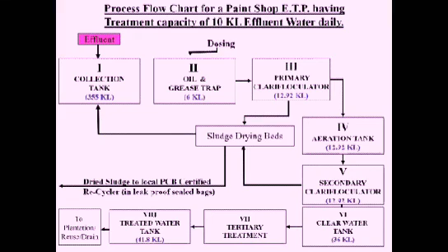This, in this case, is having 36 kL capacity. From here, if we are not attempting to make this water potable, we can directly use it for plantation or reuse it in any of the utilities in our factory organization, or we can put it in the stormwater drain also, in case, of course, the water parameters are within the compliance norms of the CPCB or State Pollution Control Board.